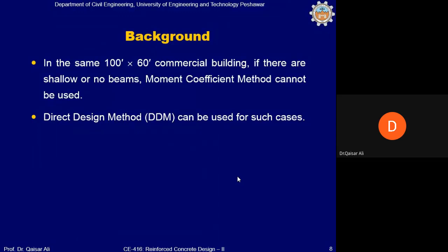The dead loads are calculated very easily from the member dimensions and the density of material, and the live loads are taken from the ACI tables. Then in the third step, the system is analyzed. And the fourth step is the design step. In the design step, basically, we calculate the reinforcement As, and the reinforcement is then converted into the diameter of bar and the number of bars or the spacing of bars.